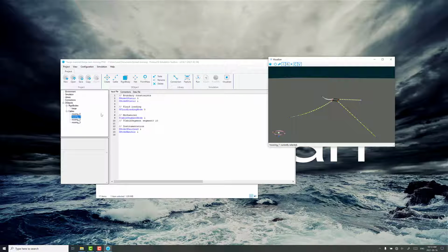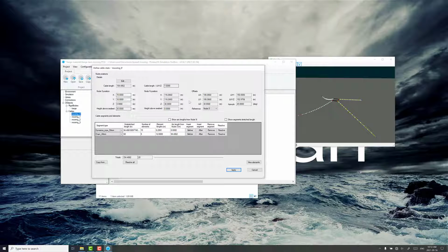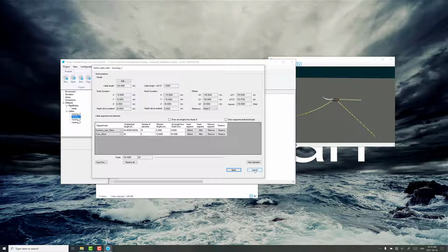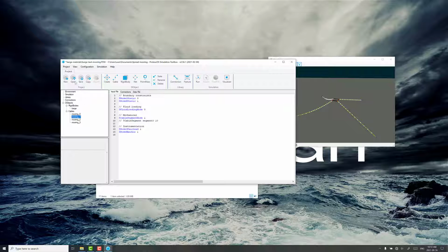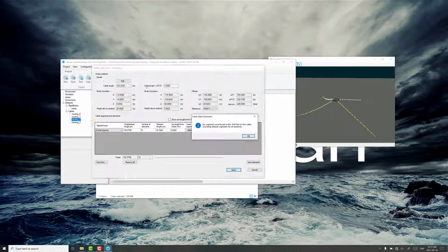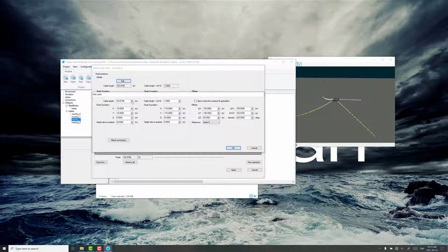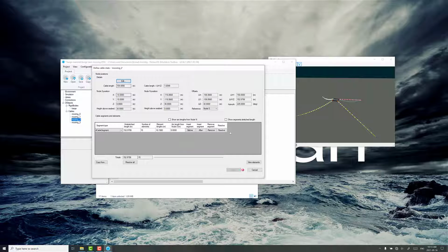Looking good, a little bit more realistic. So we're not getting any error messages or warnings when we look back at the ones that we've already adjusted because it's set up properly using the new state generator. And we just go through and do the other 2 mooring lines. So state, okay, edit the curve, change this to 1.01 and eject the nodes. That's all we need to do. There's a little adjustment in length.